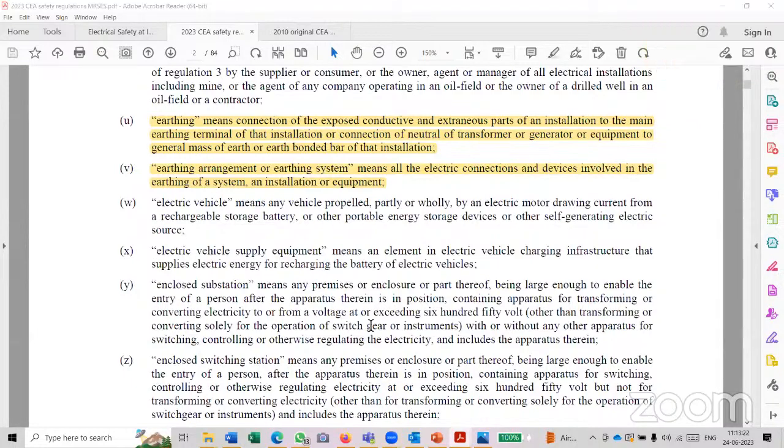Actually, it is talking about two connections. The requirement of two connections means two different protective conductors which are taking you to the earth terminal, the earth electrode. Sir, this has some technical background as well. For example, when these two connections were introduced, maybe in the 1950s, there was no IP. Ingress protection did not exist, and in most equipment the earth connections were on the outer casing, for example a motor. But later, once ingress protection was introduced in the standards, people started keeping the earth terminals inside a mechanically protected place, either inside the panel board or something like that.